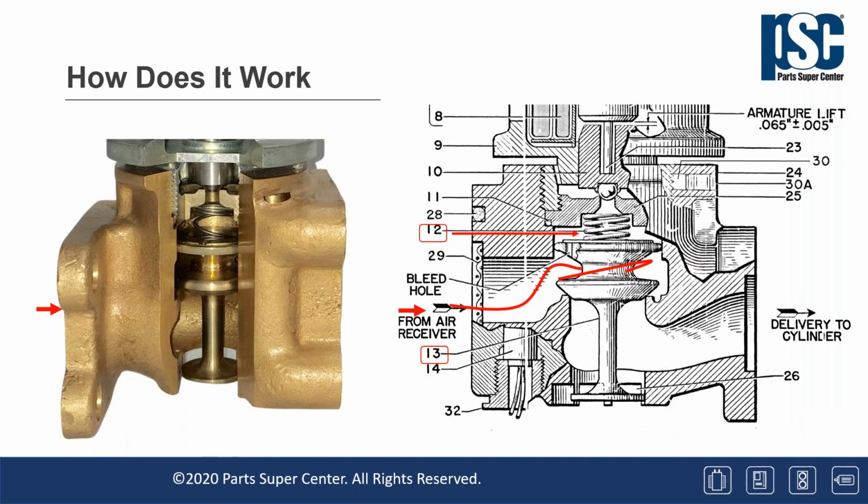As the air passes through the screen, it quickly fills the chamber and wraps around the center section between the two lobes of the main piston, which is item 13 in the lower valve body. The main piston is free to move vertically up and down in the lower valve body. It's being acted upon by the air pressure upon all the surfaces between the upper and lower lobe of the main piston. Since those surfaces are approximately equal in area, the piston will tend to stay in place.